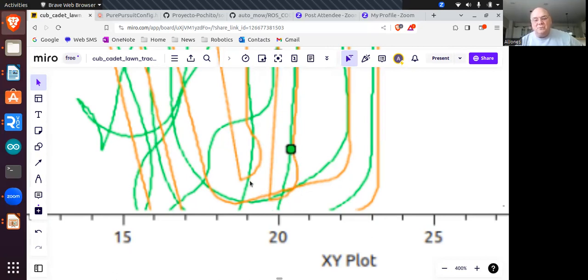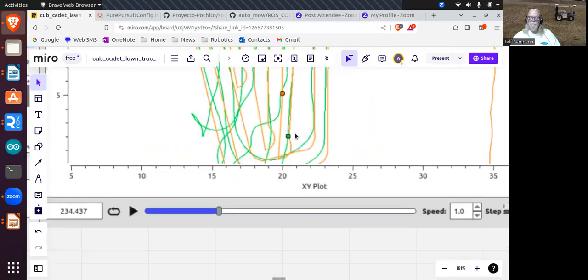And so the path is as it was in the previous diagram, but then when it actually runs in this orange, which is a ROS bag recording playback, the look ahead point, once it gets there, then the next look ahead point will come up here somewhere. Okay. And then the green is the wavy part as it's trying to get back to this look ahead point.